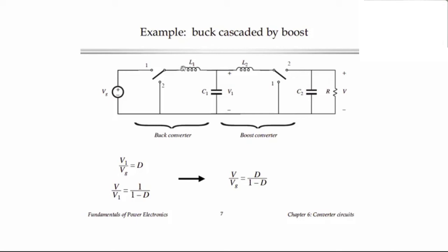And for one thing, if you look at this inner part of the circuit, we have a 3-pole low-pass filter. So there's an inductor, then a capacitor, and then another inductor that are filtering the ripple. Now you can do this if you want, but we don't really have to. We can reduce the order of this low-pass filter, and the basic DC waveforms will be unchanged.